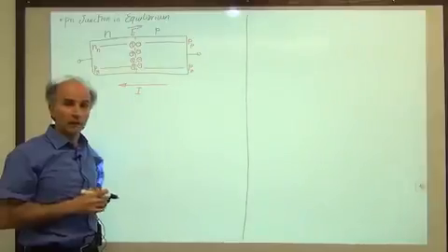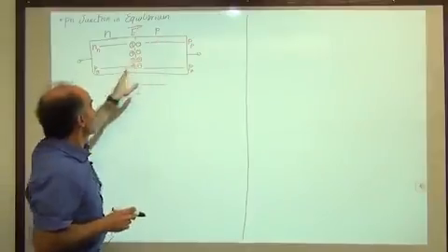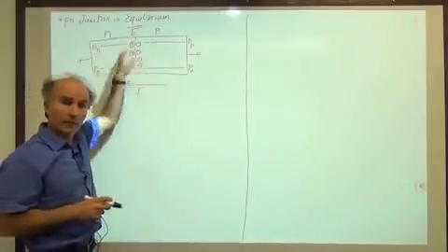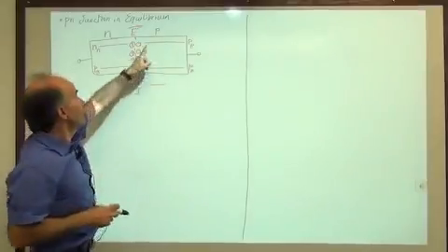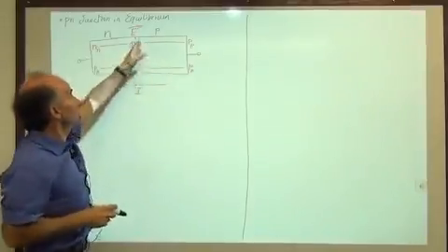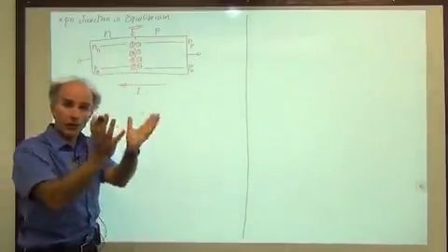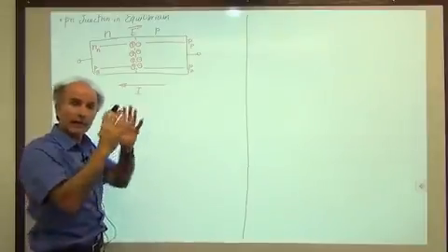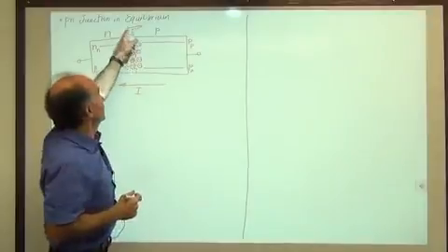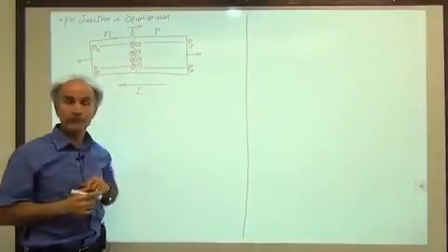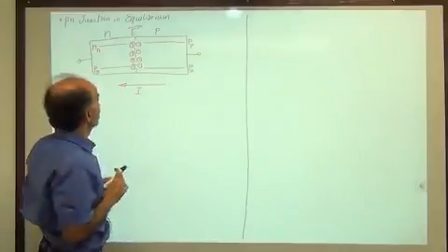Okay, so that's a lot of information coming through. We saw that we had a diffusion of holes and electrons, which resulted in a current. At the same time, as these carriers were moving, they were leaving behind ions, and these ions formed a space charge, and that space charge starts creating an electric field. So we have an electric field going from left to right.